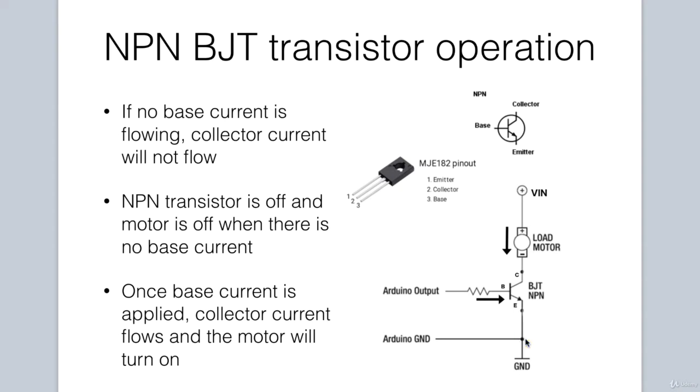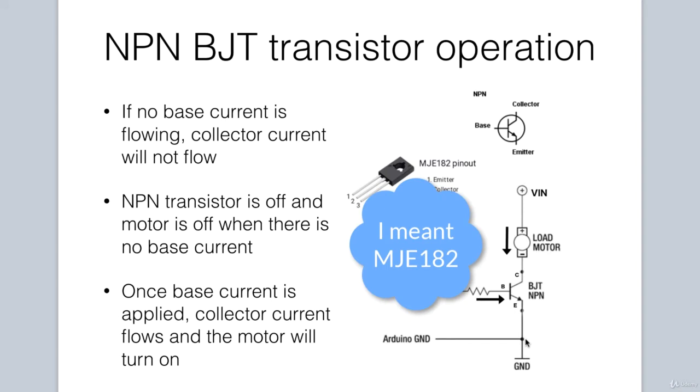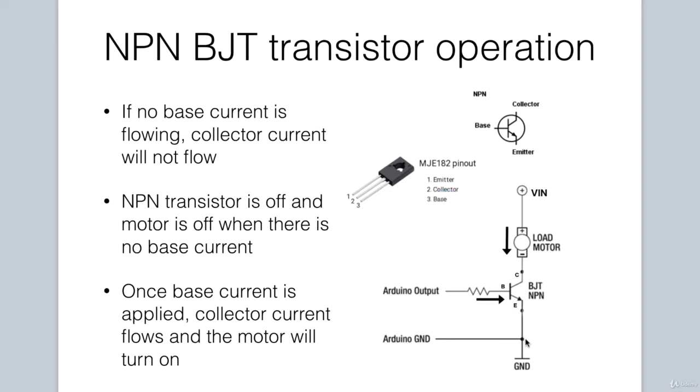The fan turns on. We are using the MJE182 NPN power transistor as it can handle higher currents and voltages passing through it. We are actually incorporating pulse width modulation as well to control the speed of the fan. The longer the on duty cycle that is applied, the faster the fan spins. We will see this in more detail later on when we examine the code.